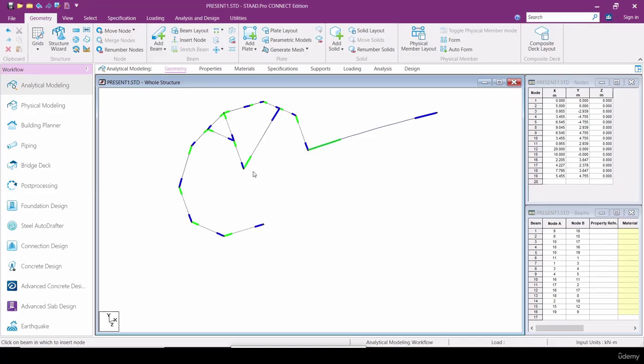I think all of you have some knowledge about AutoCAD, right? You all know the stretch command. So what is the stretch command? The stretch command will lengthen anything. If you want to shorten one thing or lengthen one thing, you have to use the stretch command in AutoCAD. In a similar fashion you have to use the stretch command here. So if you want to elongate or lengthen this beam up to this beam, you have to use the stretch command.